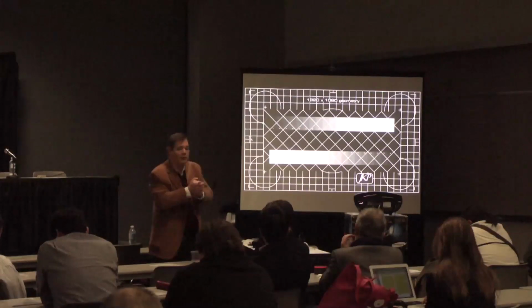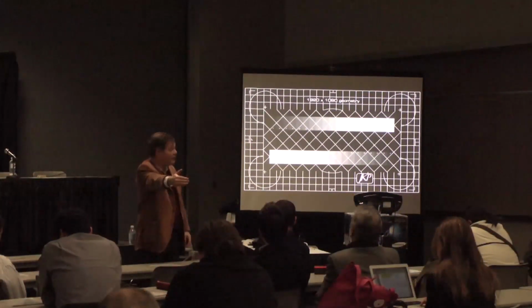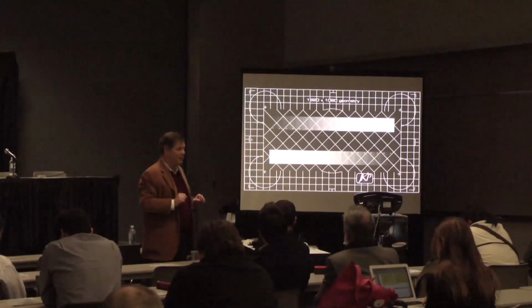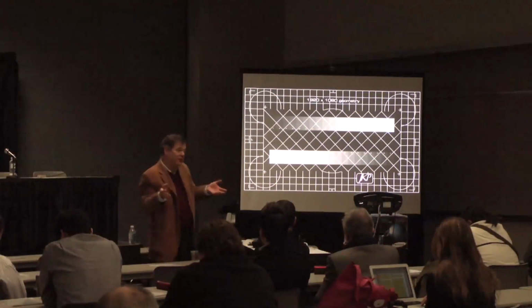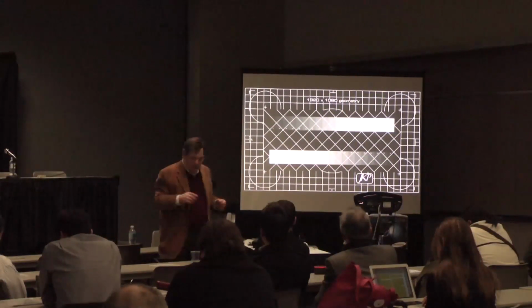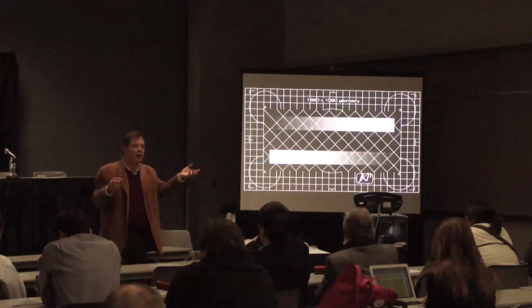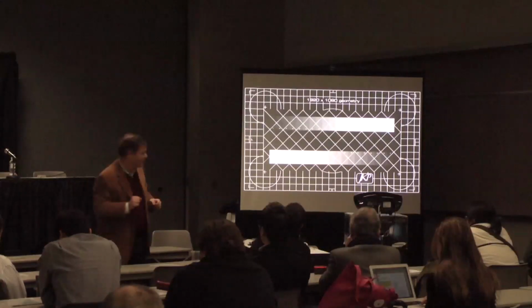Now, that's part of the reason that this particular manufacturer recommends that you be way far back, because if you're way far back, then all the lines will appear to be in the right place, and the ghosting has been minimized. But of course, at that viewing distance, you can't see the detail anyway. All right, so there is ghosting because parts of the left image get into the right eye and parts of the right image get into the left eye.